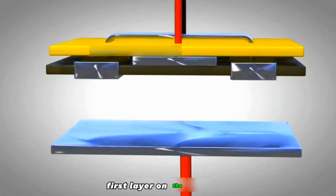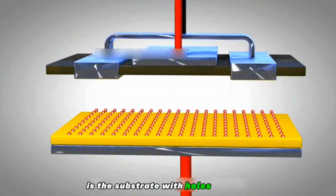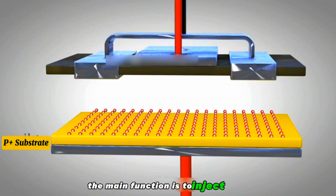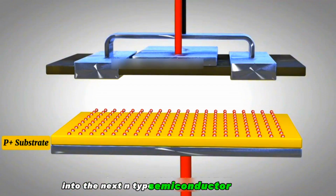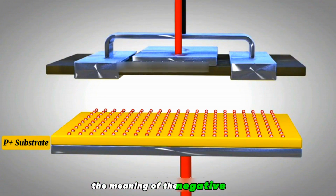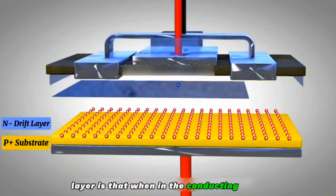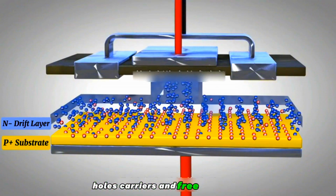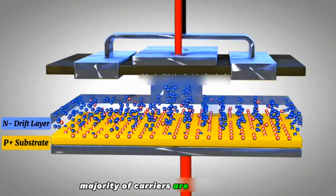The first layer on the collector is the substrate with hole carriers. It's also called the injection layer. The main function is to inject holes into the next N-type semiconductor drift layer. The meaning of the N-negative drift layer is that when in the conducting state, there are 2 kinds of carriers in this layer: hole carriers and free electrons. The majority of carriers are free electrons.